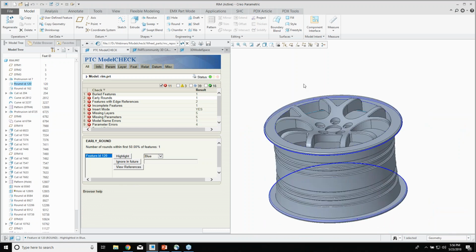The reason why I would enforce this rule is if I'm working with mold components, if you add certain rounds too early in the design, as soon as you start adding your draft features, for instance, then your rounds start giving you issues with the draft feature. So this rule will force me to have my draft features first, and then I can go over to the rounds. Yeah, so that's just one of the examples I use quite a lot. And you can work through this.